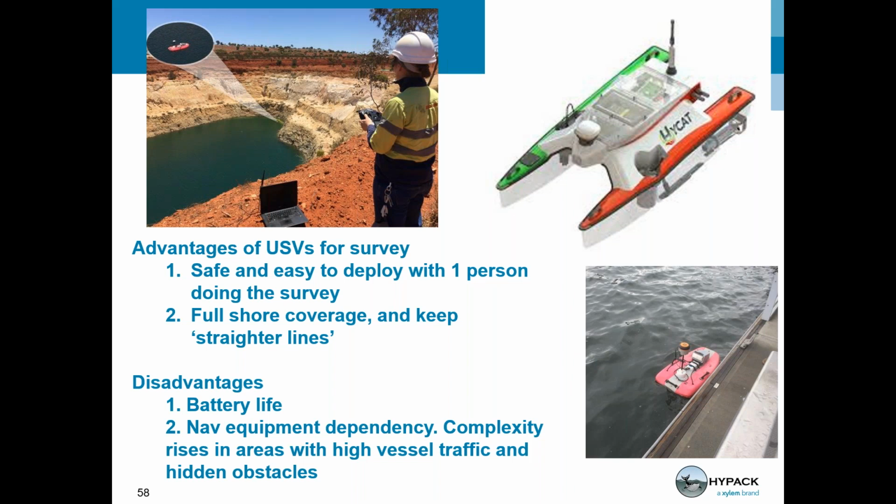There are a few disadvantages, of course. One of them is battery life. This has been improving steadily over the years, but of course, there's still a lot more that can be demanded of it. Another thing is nav equipment dependency. For USVs that are not remotely controlled and are autonomous, the complexity usually rises when you have high vessel traffic, or hidden obstacles that you had not planned for. These are still being worked on and improving every year, but generally speaking, it's easy to foresee that in the future 80 to 90% of surveys will start being done by USVs. Can I have the next slide, please?